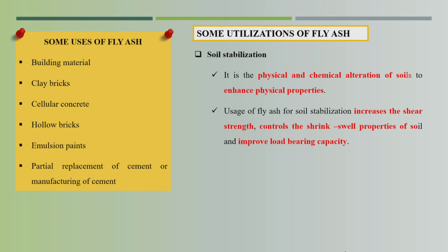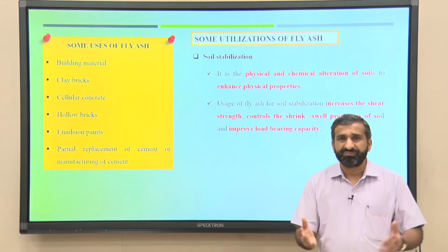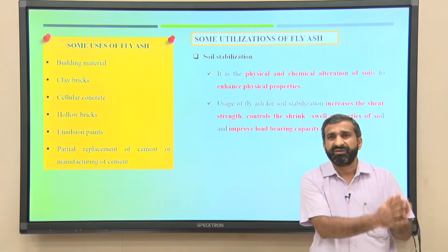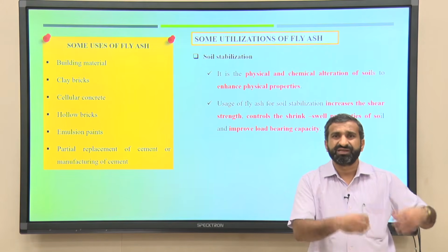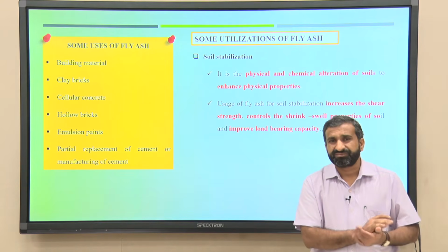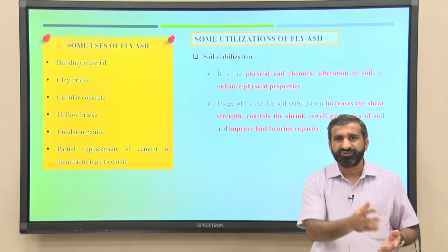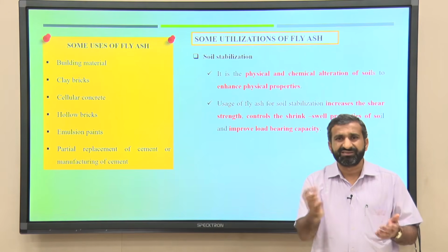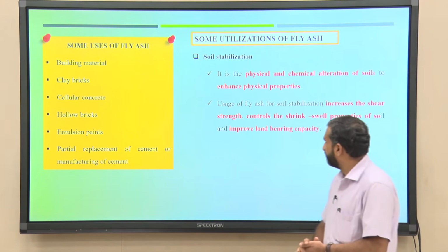So, it is also possible, and suppose somewhere some particular kind of embankment formation will be required, requiring a large amount of soil. This bottom ash could be utilized to replace maybe 10% or 20%, depending upon what exactly the compressive strength or strength of that particular embankment is required to be. But again, the same point I am saying, do the leaching experiments, and if it is under the standard, we can always use it for such purposes.